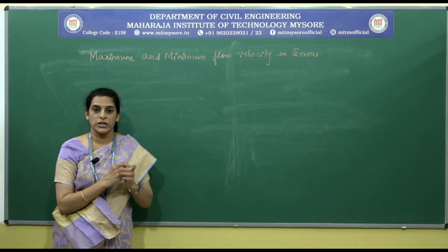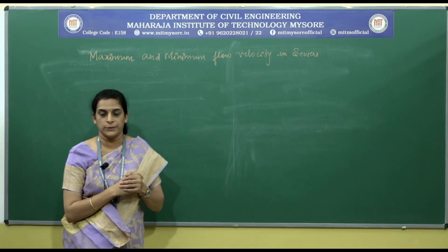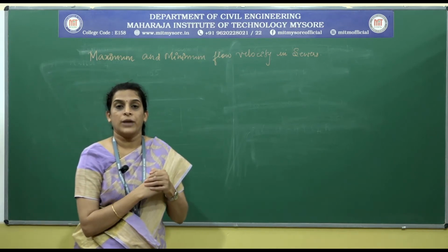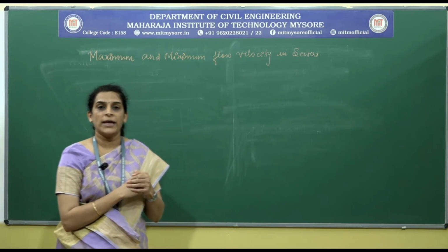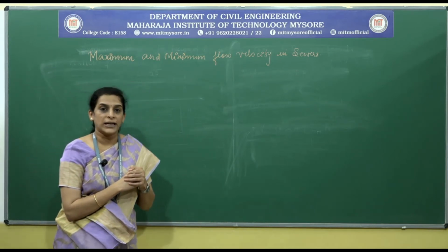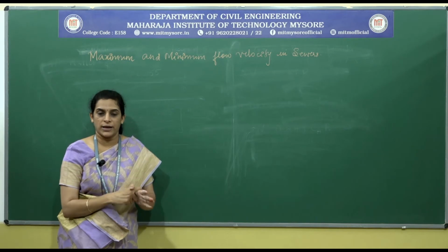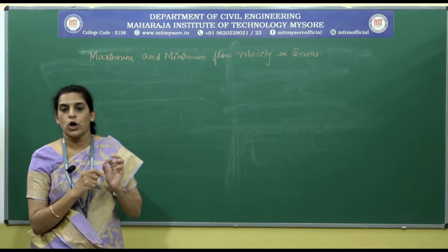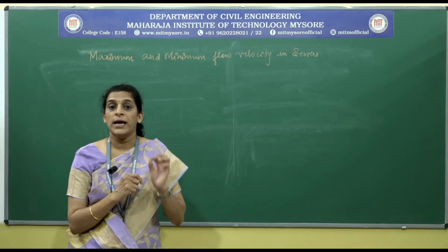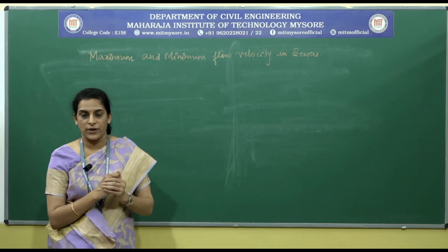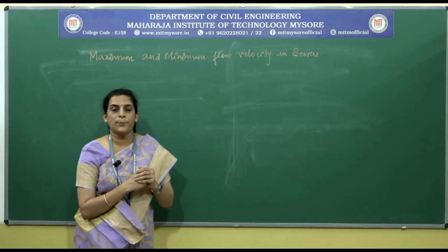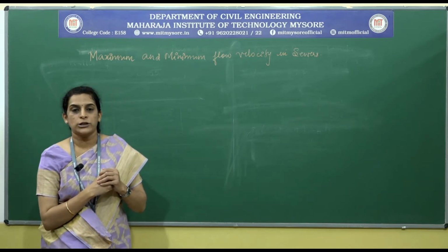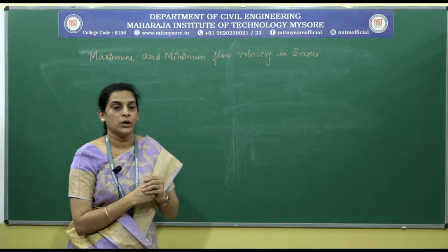There shall be fluctuations or variations in the supply of water. Hence, we cannot achieve the self-cleansing velocity as a constant throughout. It varies, and very importantly, at least we should achieve self-cleansing velocity once in a day, so as to make sure that there won't be deposition of any of the particles inside the surface which will clog the sewer so as to make it non-working or so as to reduce the efficiency.